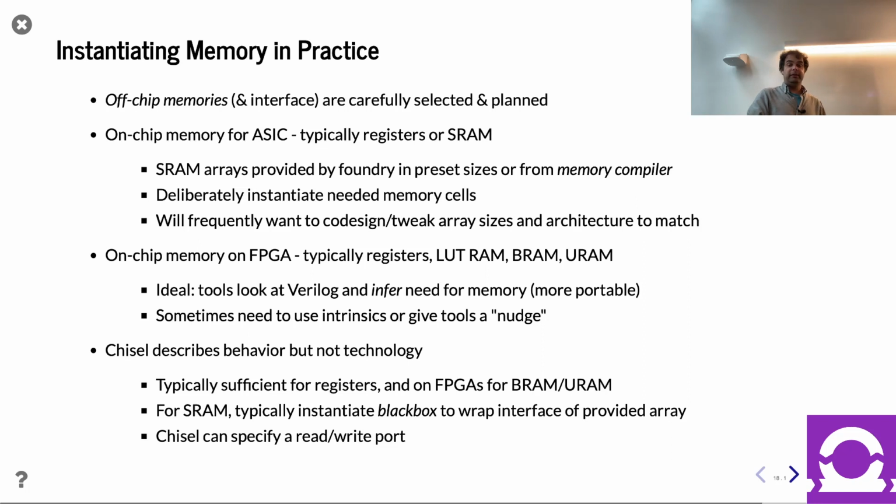Interestingly, in FPGAs, you have a lot more choices, which is kind of surprising. You think it would be reversed, right? But in FPGAs, you have registers. You can turn LUTs into LUT RAM, right? You have BRAM or block RAM, and even sometimes URAM or UltraRAM, right?